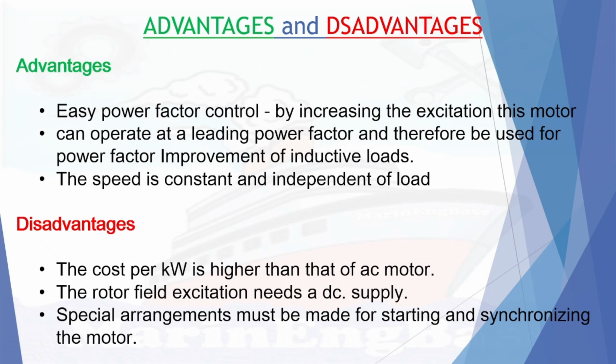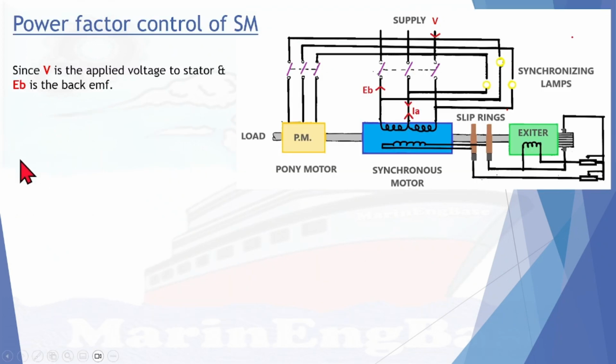The disadvantage is the cost is high, the rotor needs an external excitation system, and special arrangement is needed for starting. Okay, these are the disadvantages of the synchronous motor. Let's see how to control the power factor.